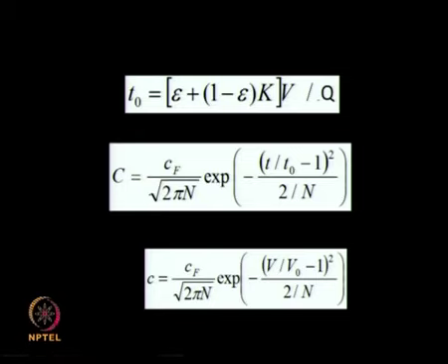So we looked at a few problems in the previous lecture on how to make use of these equations to calculate the number of theoretical plates or stages if I know the standard deviation of my normally distributed curve, as well as the retention time.